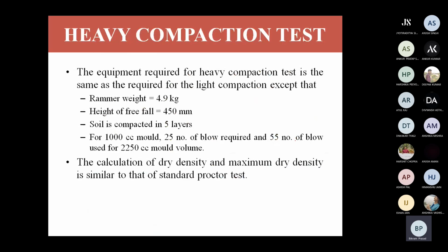So now heavy compaction. I already told you the equipment required for the heavy compaction test is the same as for light compaction, but the rammer weight is increased and the height of fall is increased. Soil is compacted in 5 layers.